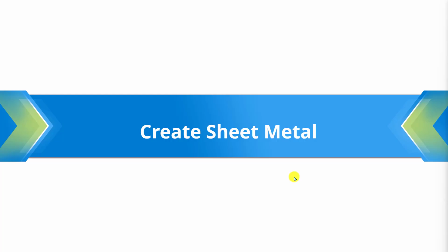Alright, in the last chapter, we discussed how to define the global attribute. Now, assuming everything is ready, we can start creating a sheet metal part. So in this chapter, I'm going to introduce how to create a base and the various flanges.